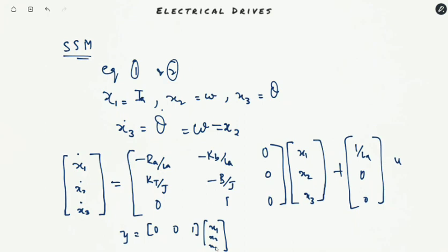So these are the transfer function models and the state space models for the speed control of DC motor drive and for the position control of DC motor drive, while assuming that the field circuit is constant. So mostly we'll be adopting armature control methodologies, widely adopted as compared to the field control method. We tend to control the armature voltage of the DC motor through power electronic devices. We do not go into the field current control of DC motors.